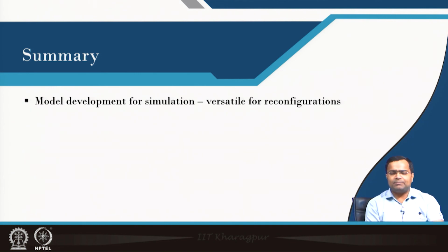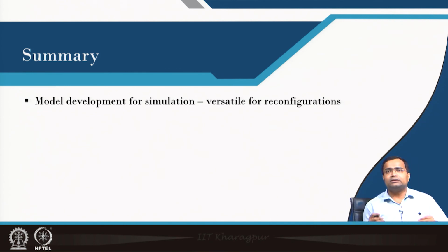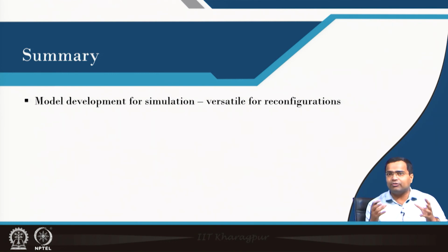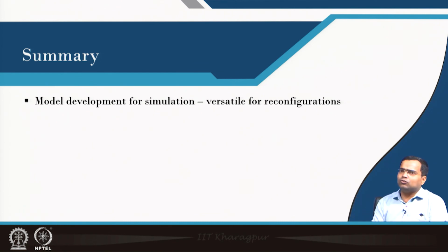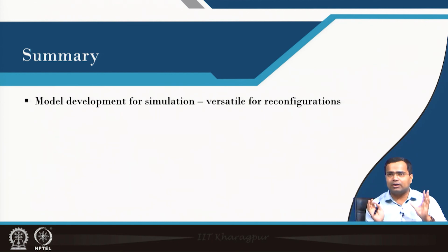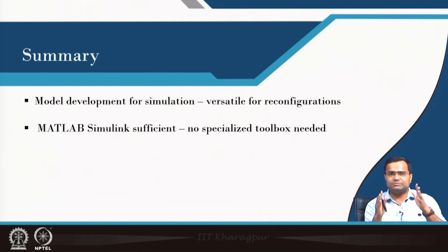In summary, we have discussed model development for simulation, and these models are versatile for reconfiguration. In fact, they are plug and play type blocks. If we want to implement multiple converters, we can plug in these blocks and create a subsystem. If we want to realize more complex converters consisting of more energy storing elements, we know how to implement each individual storing element's differential equation into a Simulink block, then we can simply keep on adding blocks. MATLAB Simulink is sufficient. We do not need a specialized toolbox like SimPowerSystems or other toolboxes.